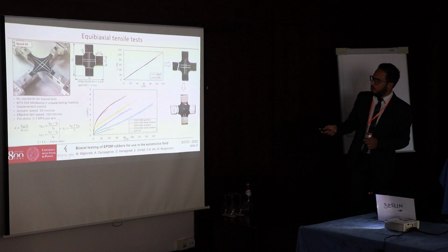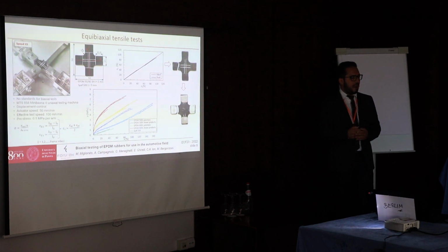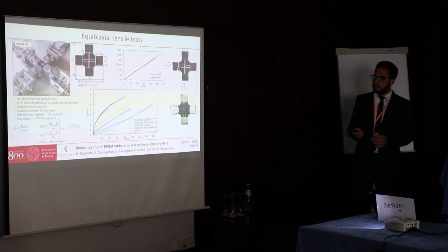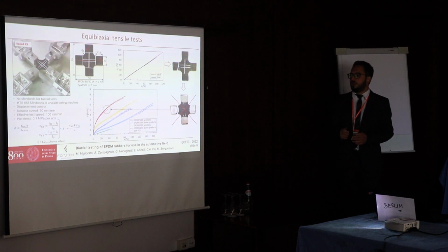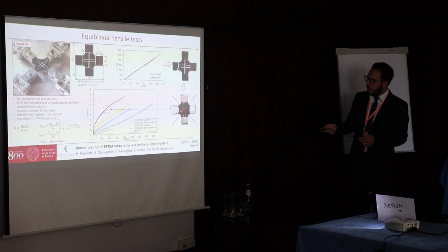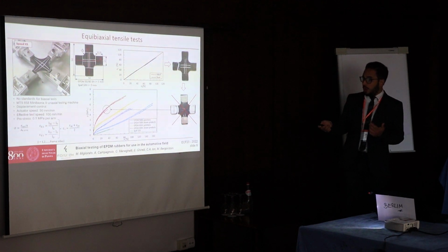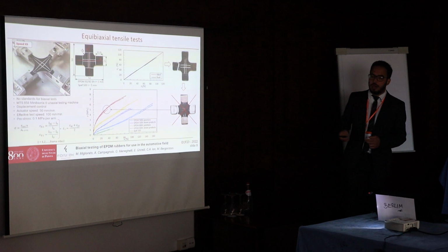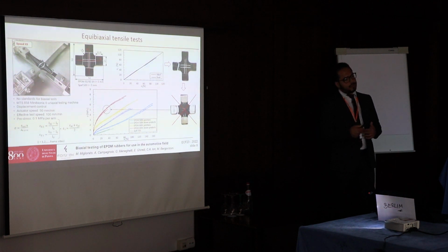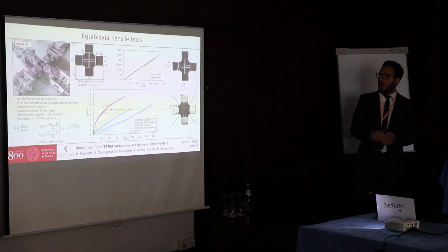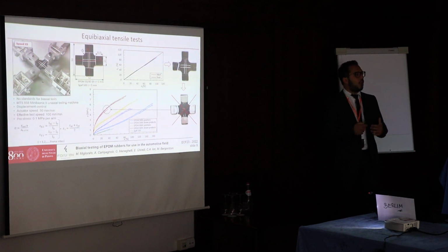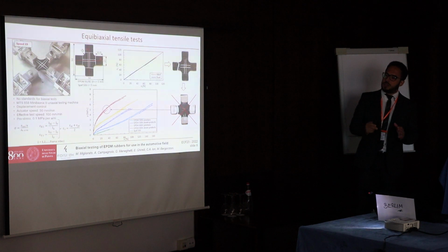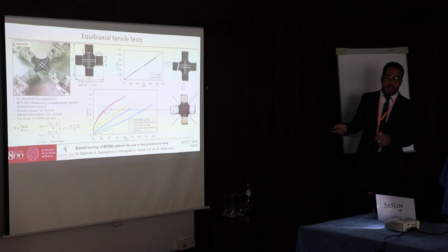Even the use of aluminum plates glued to the gripped area in order to reduce the stress state in that region does not allow inducing failure in the center of a specimen. Conversely, they generate a premature failure. So an optimized specimen geometry should be developed to induce failure in the center of a specimen to get failure data under equibiaxial loading.